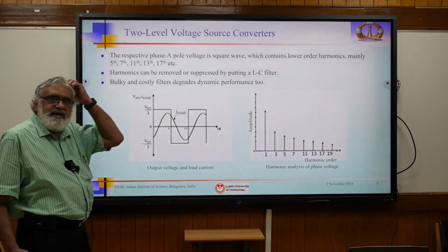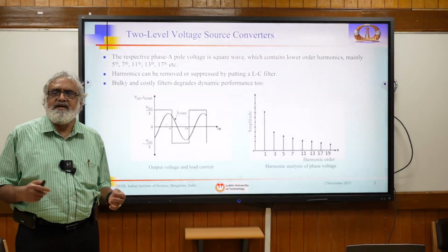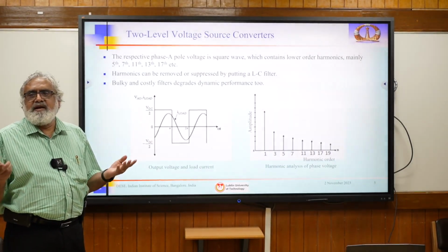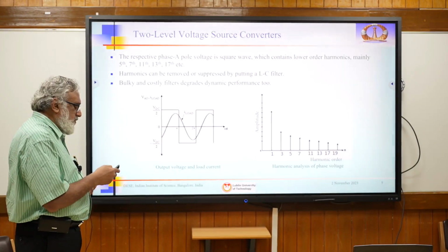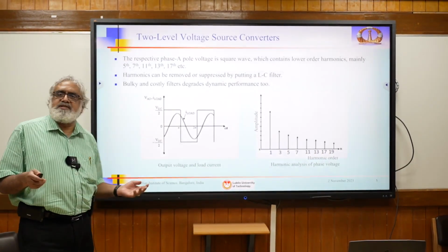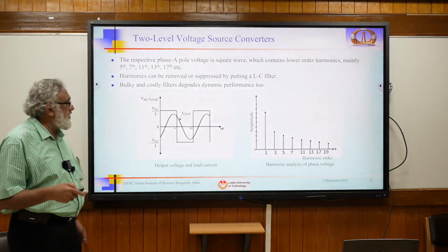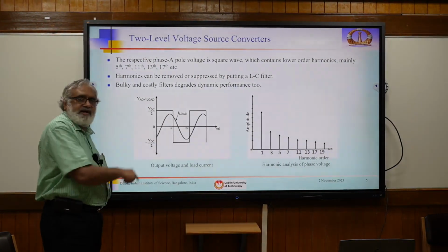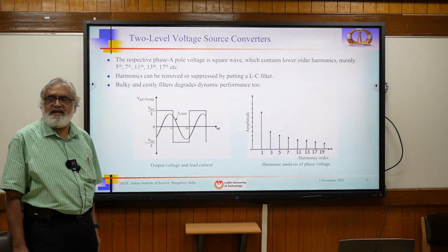So let us take a DC to AC converter, the basic DC to AC converter. If you see the normal single phase half bridge converter, if you use it and switch it as a square wave, this is also an AC waveform. If you do the Fourier series, you have all the harmonics, right from the fundamental to the 5th, 7th, all these harmonics are there.